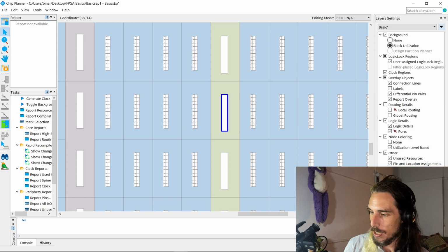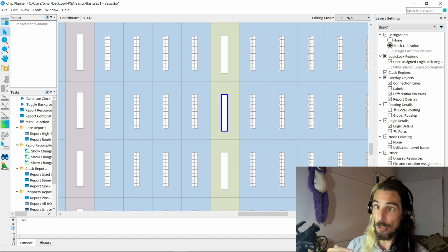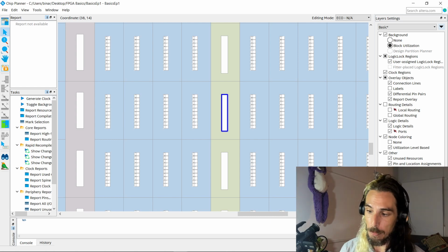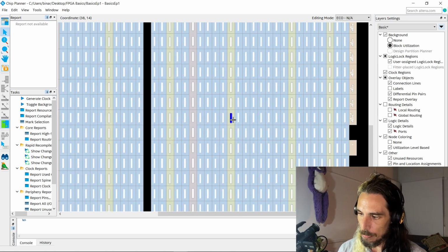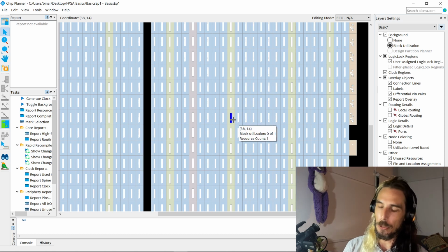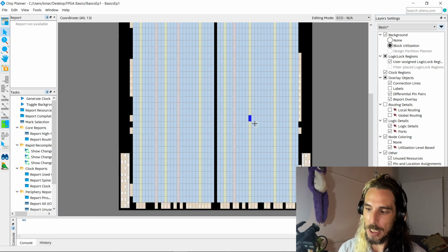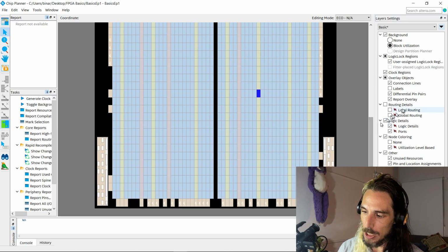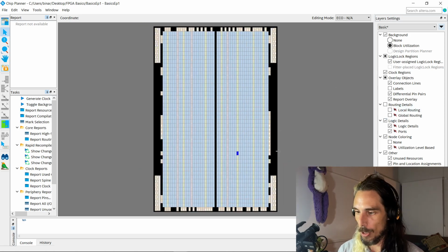There's various different ways they can be used, so you can have two different systems connected to the same bit of RAM, both operating at a different clock rate and both able to read and write from it at the same time. So they're really flexible like that, and have a whole bunch of different uses depending on how they're configured. So again, everything on the FPGA is aimed at being incredibly flexible so that it can be suited to whichever particular project you want to throw at it.